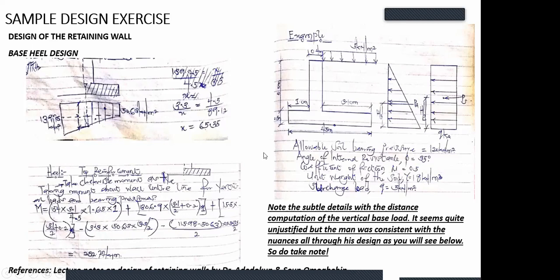They are the normal way we do things. For my vertical edge, we're only taking vertical and base pressure. We've taken the vertical base load. Now let's take the vertical edge pressure, which is 306.9. But you also have to remember that your vertical edge pressure is acting directly on 3.1. So it's very clear that it's acting at the center, which is 3.1 over 2. So it's acting at 1.55.